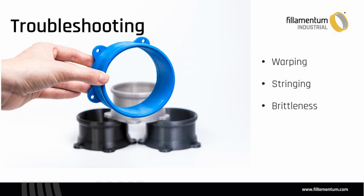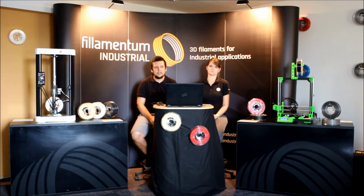Also, a common problem with nylons is stringing. If you are printing small parts with small features or several small parts, and you are seeing spider webs between the parts or features, usually it's connected to humidity again.